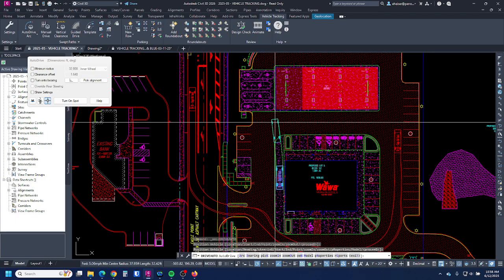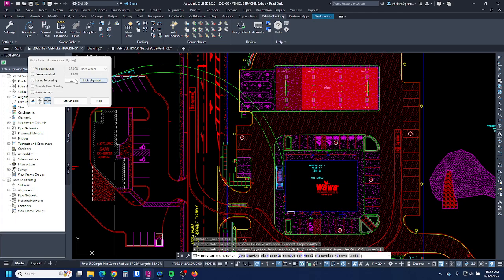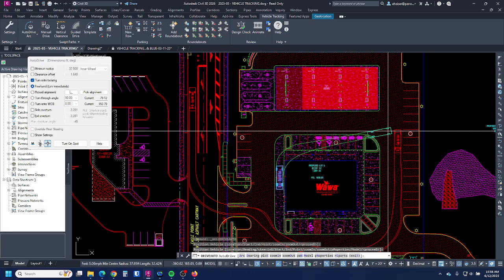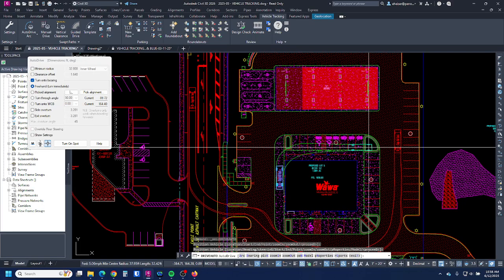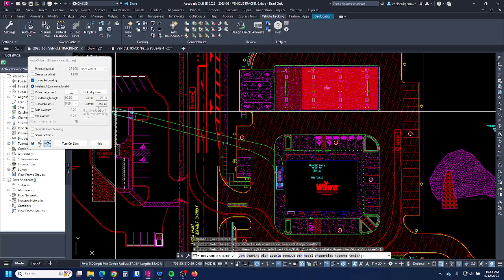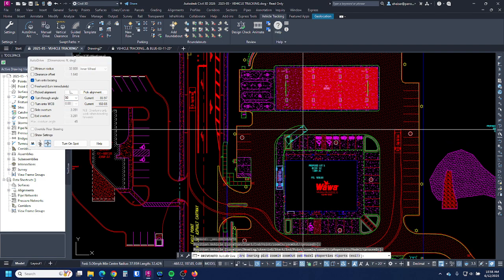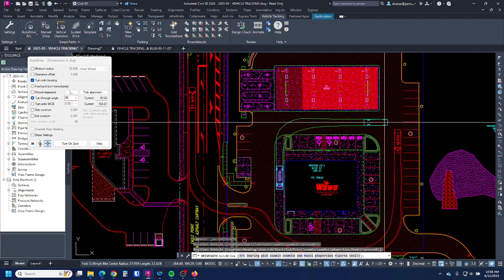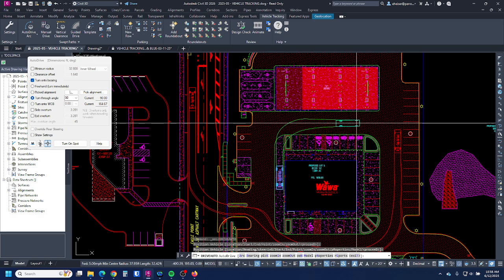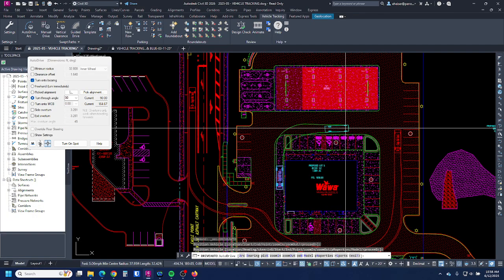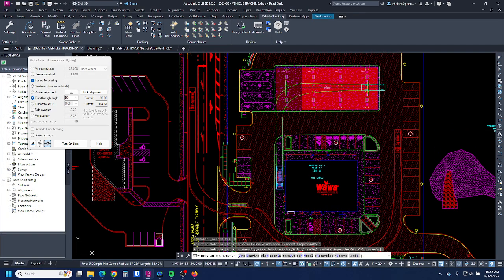First thing I want to show you is how to turn onto a bearing. So if you go into the dialog box and you check turn on to bearing, the vehicle starts to behave differently when you move the mouse around. What I like to do after I click turn on to bearing, I don't like the freehand. I like to do turn through angle, and then you can specify what angle you want. Most likely when I do this, I'm doing a 90, and it could be for entering a driveway a lot of times, or if you're navigating a parking lot that's all 90-degree turns, I can use it for that.